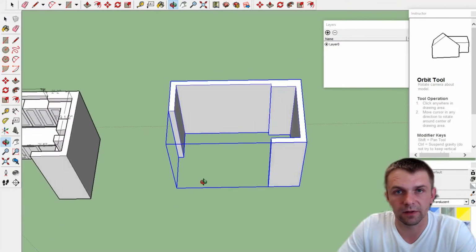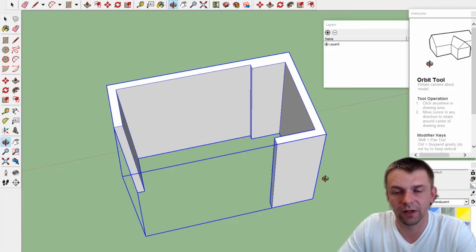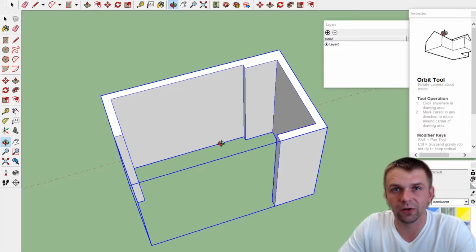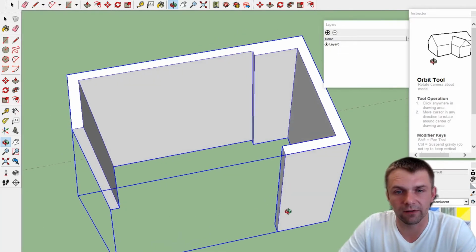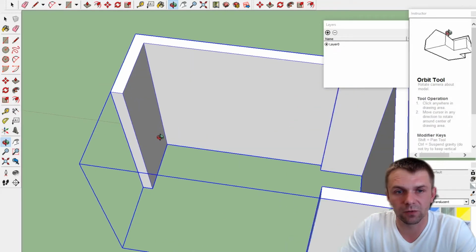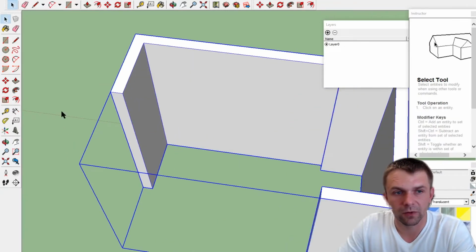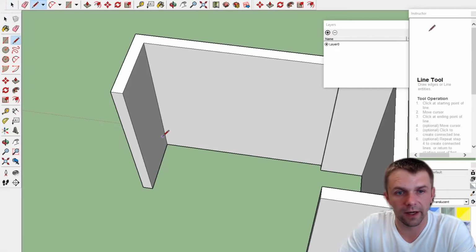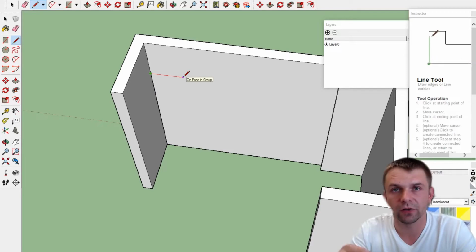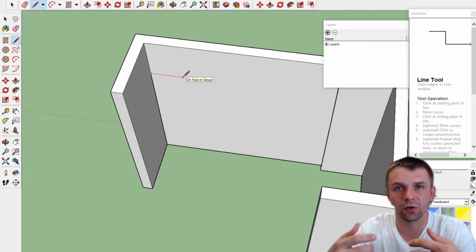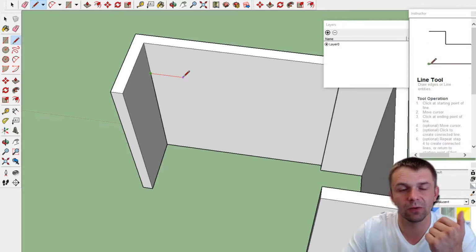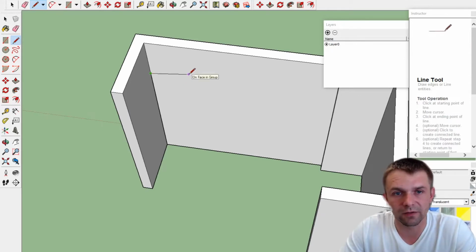This is the number one thing you have to practice and learn, and when you know this, it's much easier to start laying everything out after. So we'll start from this wall. We have a fridge. When we have a block, we go back to the line, we press L. Let's say it's a 72-inch tall fridge, 33 inches wide. Here it's very important to know how the fridge is opening, how much clearance you need from the wall. So you have to review your specification.